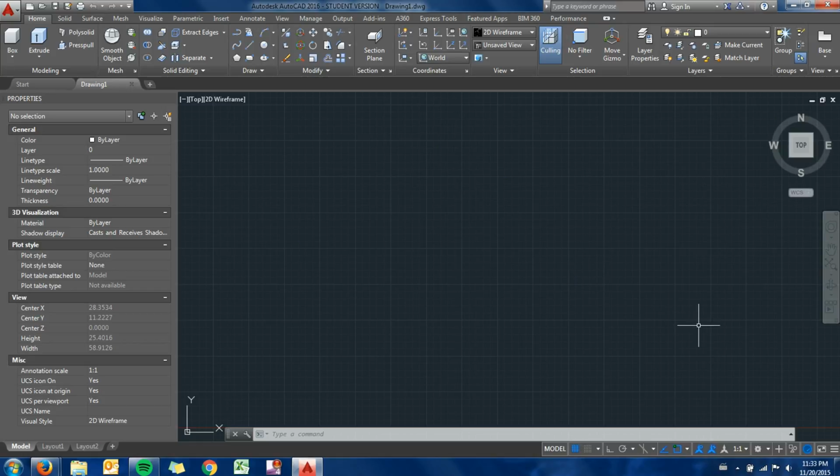To get started, what I would recommend doing is changing your workspace. I can come in another little gear. I'm going to change out of Classic into, you can see I've already changed into 3D modeling, which gives me this ribbon up here with a whole bunch of three-dimensional drafting commands. Or I can use 3D Basics, which just sort of minimizes what it thinks I will need and just gives me a fraction of these commands. So I'm going to stay in 3D modeling.